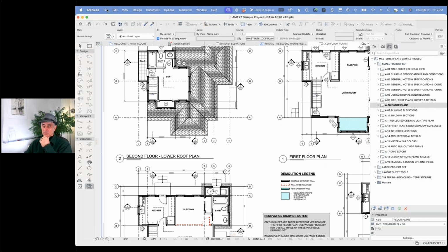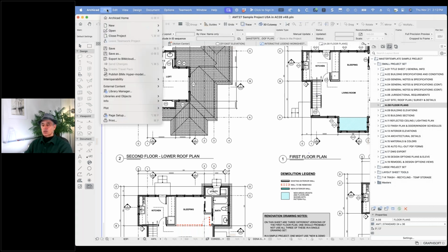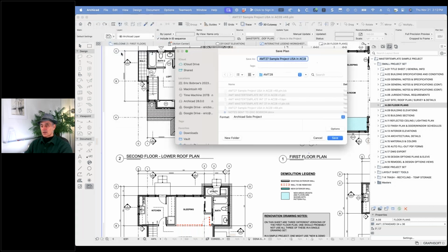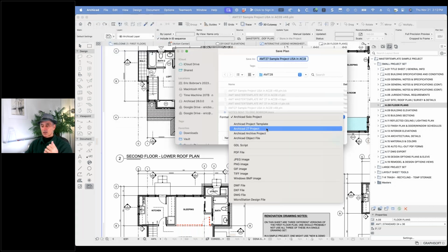If I wanted to save out to Twinmotion, there would be a few different ways I would think of testing it. I have not looked at it. If worse came to worse, I would go Save As, and then save as a solo project in 27, and then in 27 use the export. Now, there are some limitations there. If you are using the new global libraries, those parts probably won't go backwards. That would be an issue, saving it back in an earlier version. All the library parts like windows and doors and stuff would disappear. So I wouldn't do that.